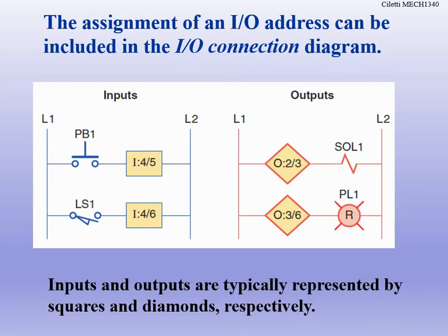Make sure that you have the right address for each thing, and to know what's going to get what address. Now, when we're programming on the 870 trainer, those already have predefined addresses for all the inputs and outputs. All right, so the limit switches have a specific address. The solenoid coils have a specific address. So there's a list of those at each station so that you know what you're programming. So you don't just get to make up an input and an output. It's for a specific component when we actually get on the trainer. So everything's going to have its own unique address.